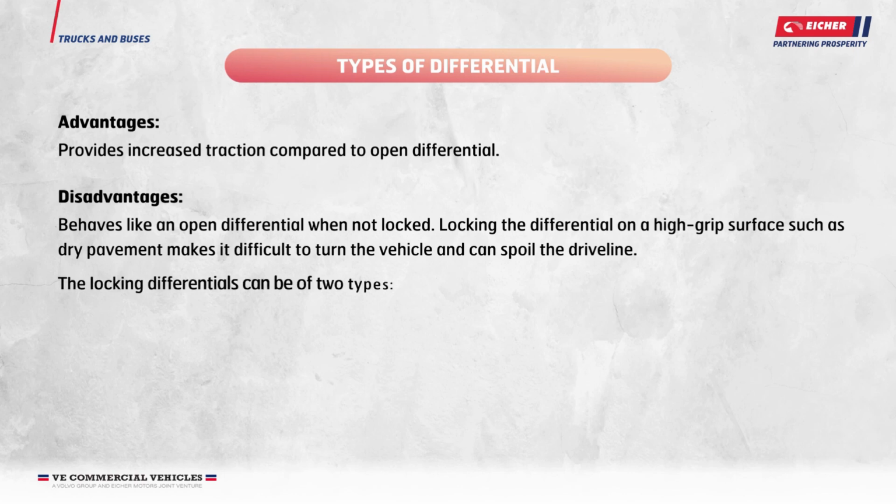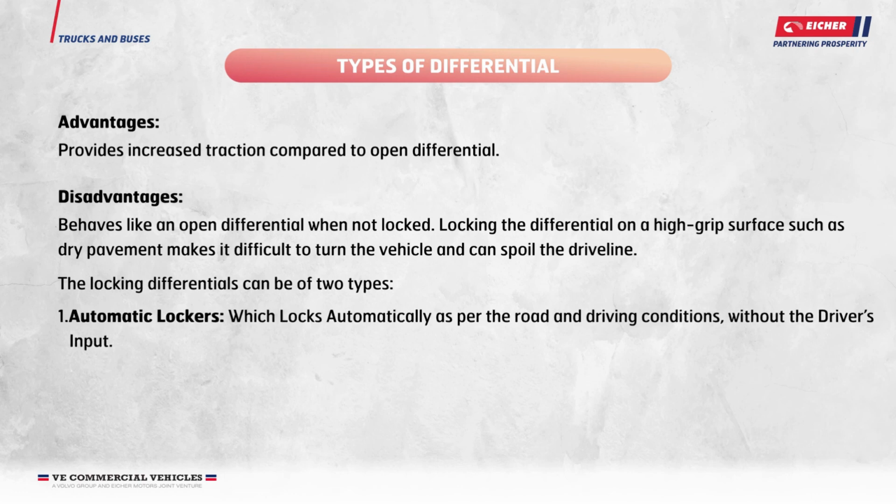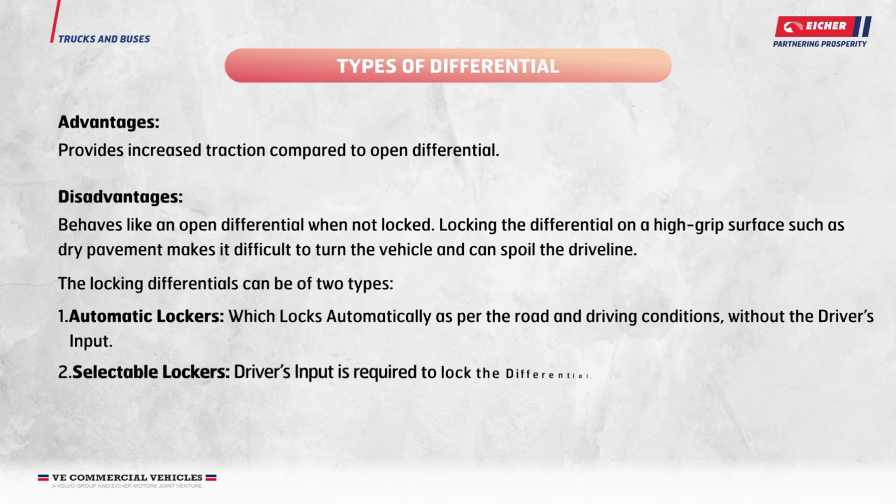The locking differentials can be of two types. Automatic locker, which locks automatically as per the road and driving conditions without the driver's input. Selectable locker. Driver's input is required to lock the differential.